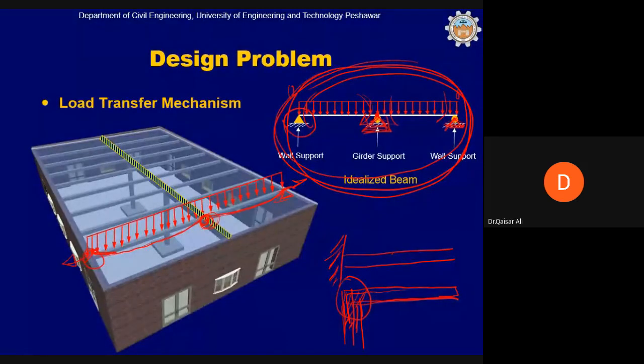Okay, so hinge support will offer resistance to this thermal movement. However, from a practical point of view, we know that whenever there is a thermal movement, it cannot be completely resisted by the walls, especially when the beam is supported on the walls and only friction between the beam and the wall is responsible for resisting this thermal movement. So this will not be possible. For this reason, we will provide one support as hinge support and the other as roller support, so that this support can move.